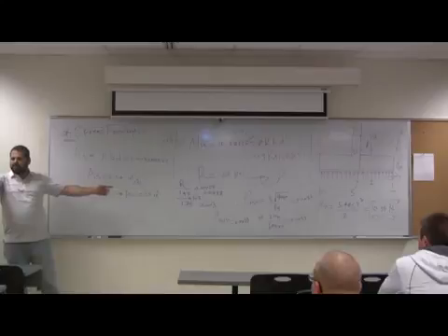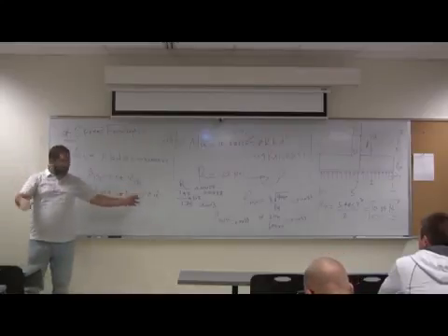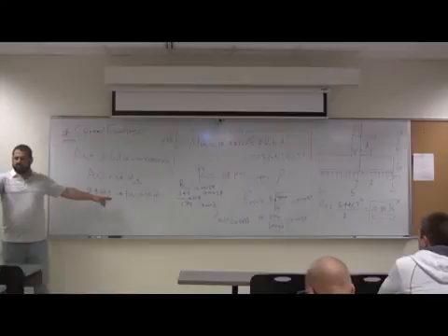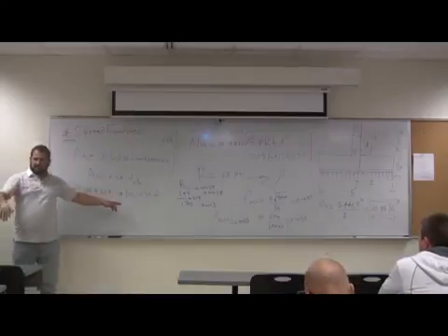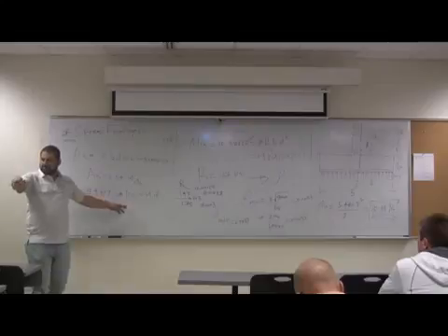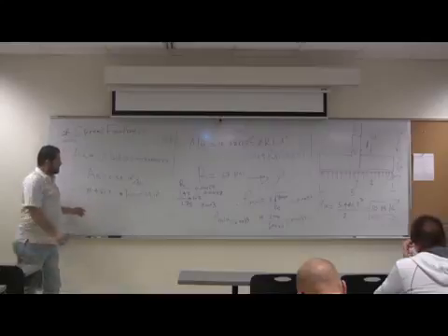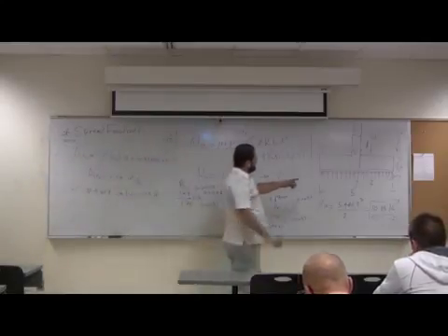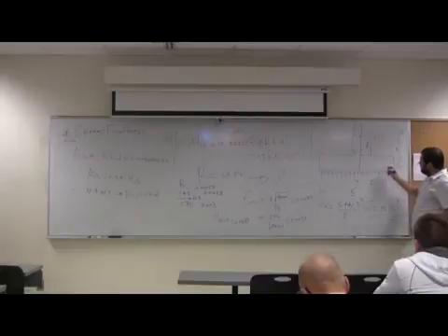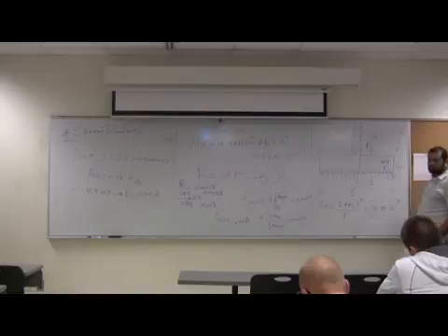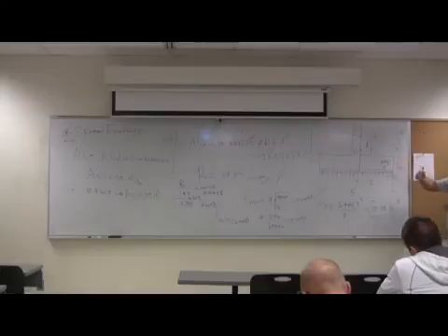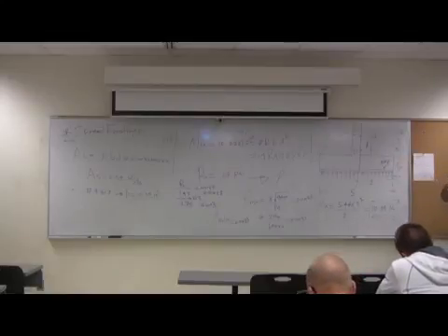Remember, the tables give you full numbers. If you want something for a half, like at 7.5, you can get it. The table has halves and gives you up to 12. If you want more than 12, I told you how you do it when we were there. So that's the reinforcement: number 4 at 7. Even our D is stronger, more than 8.5, so that's a safety. That will give you more moment and better shear resistance.